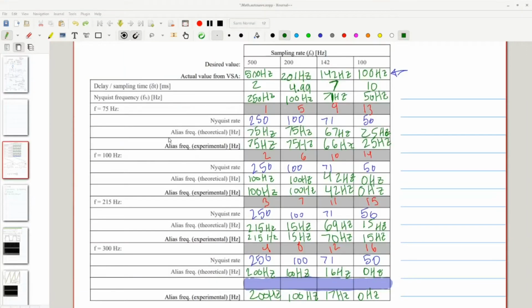To get a better understanding of how the sampling rate of a frequency input can affect the aliased frequency, I sampled a number of different frequencies with a number of different sample rates to complete this chart here. Along this diagonal here, half the sampling rate is lower than the frequency input. What this creates is a situation where we have aliasing.